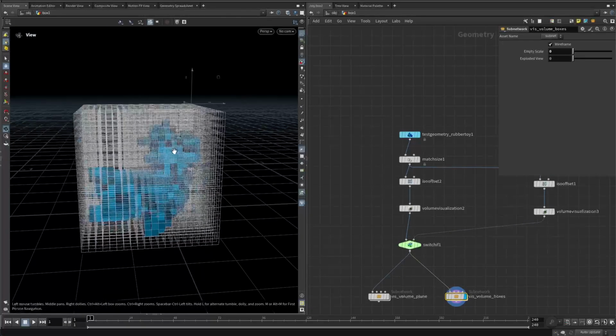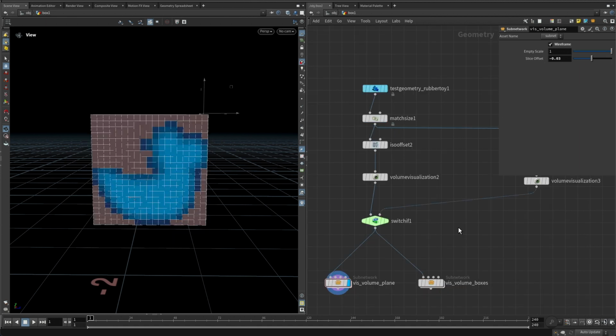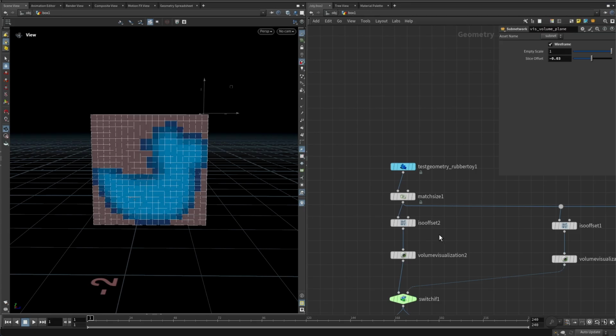A volume is also a field. A field is basically a volume of information. Just so you're not getting confused by that in other Houdini setups. So it's basically the same thing. We'll look at what you usually have in a field compared to a regular volume. But basically we tend to use fields inside a simulation, while when we are in a geometry network like this, we call them just volumes. All volumes and fields have properties that tell you what they are, and their resolution and their size and so on.